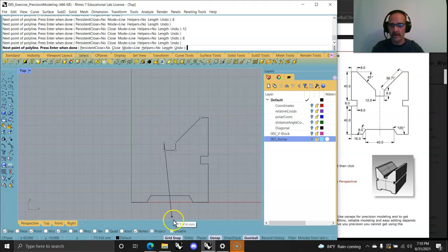It would have been smart to do half this project and mirror it, but I'm just going to continue with what we're doing. We are doing a 45-degree angle and snapping to it. And we want that distance again to be 36.77. Enter. Enter again, so I make sure I get it. And I'm going to take my, I could go reference, -8, 0. And now I can do my